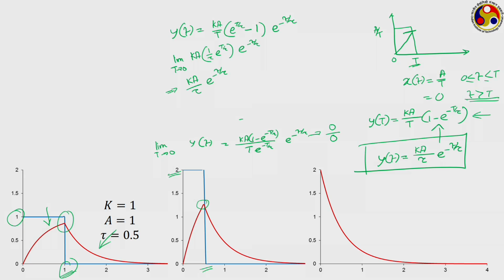Over a small duration of time the input is very high and then there is no input at all, accordingly the measurement system gives a high peak and then it decays to 0. This is the same signal, and of course we have plotted this using tau equal to 2 in this particular case.